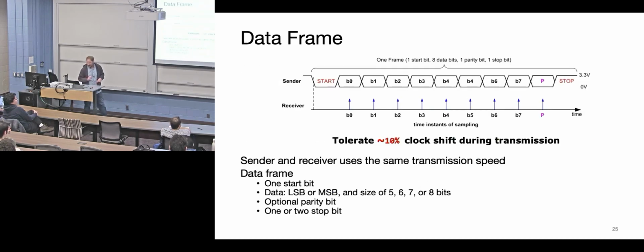We can see that here. So this is why there's built into this thing a 10% tolerance to clock shift between the two devices, because you go in through the start bit, you figure out where your sampling is, and you go sample, sample, sample, sample, but your internal clock rate that's doing this may be a little bit off. What questions do you have?